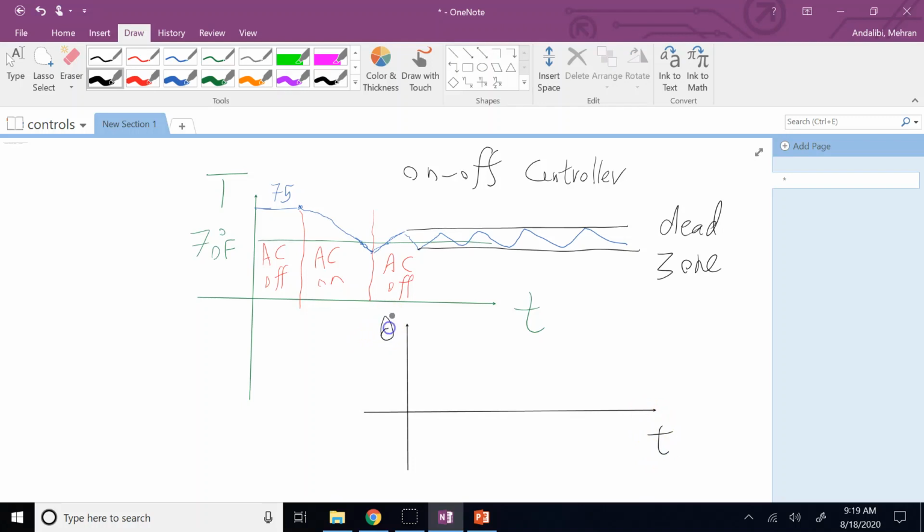So theta. When you tell it to rotate 45 degrees, you say, hey, go 45 degrees. I want it to be settled at a 45 degree angle. And right now, let's say it is not at 45 degrees, it is at 0. So it starts increasing. The PID controller, which we'll talk about, that is on this servo, basically allows the rotation to happen.